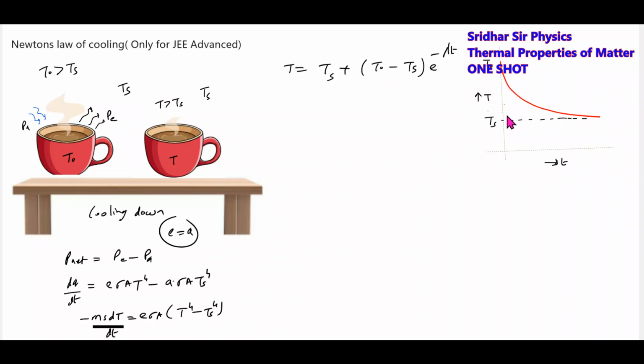Okay, fine. So this is a basic necessary condition. To solve this problem, we'll go for a generalized formula, because every time dealing with exponentials will become a big problem. This will be this one only, just modified. This will become: initial temperature minus final temperature by time interval is equal to some alpha times the average temperature difference, (Ti plus Tf) by 2 minus Ts.